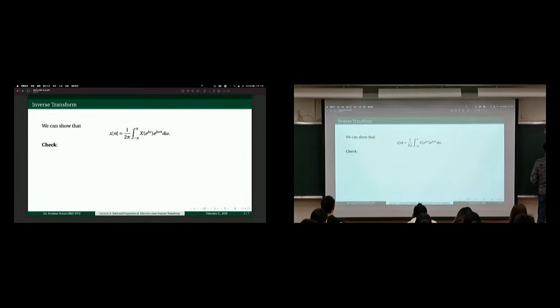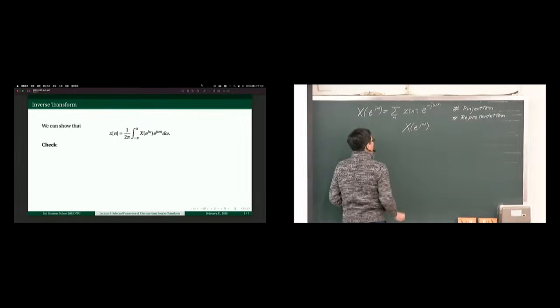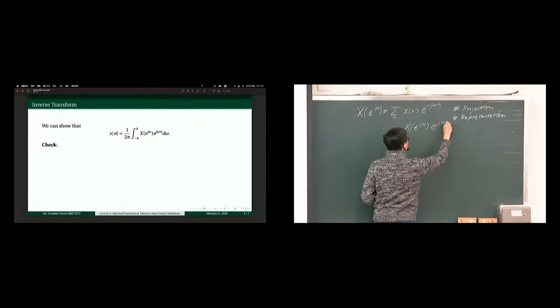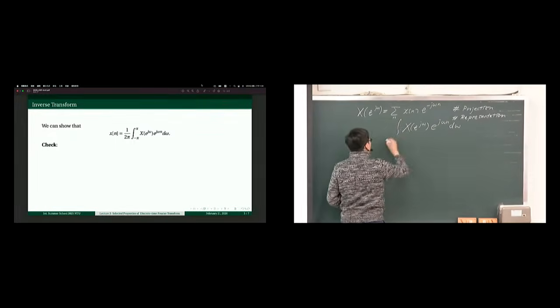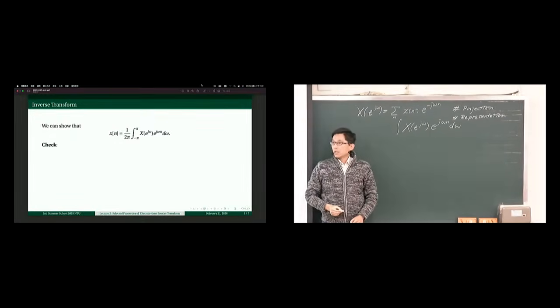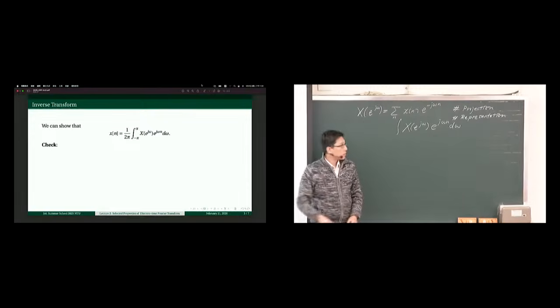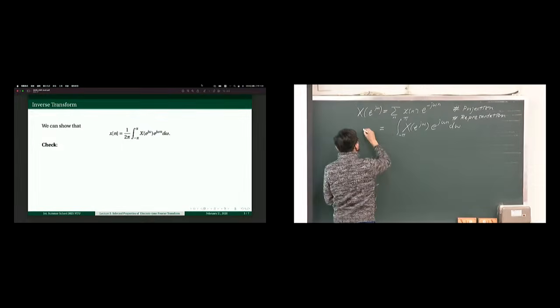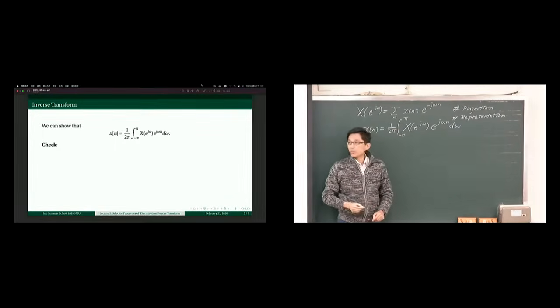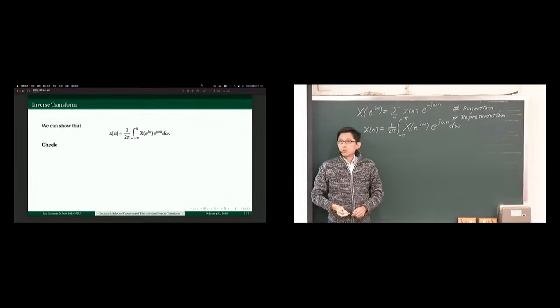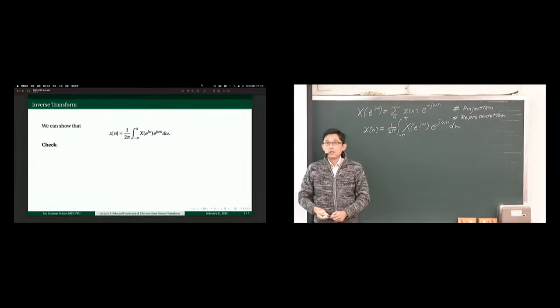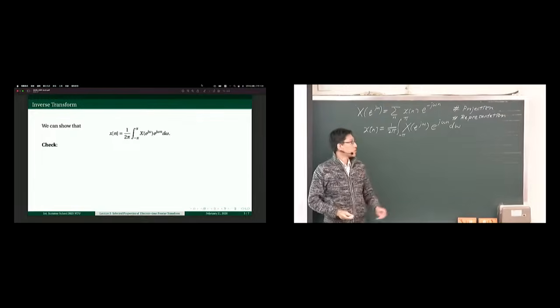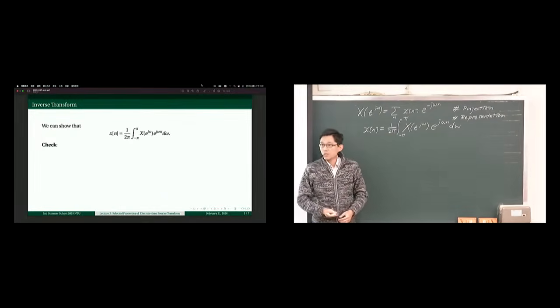Last time near the end, we also proved that the inverse transform takes the spectrum on the right-hand side and collects all the terms through an integral with respect to omega. The limit of the integral is from -pi to pi. That basically gets you back your signal in the time domain, except that there is a normalization factor of 1/2 pi. Last time we made a simple derivation involving changing the order of summation and integral.